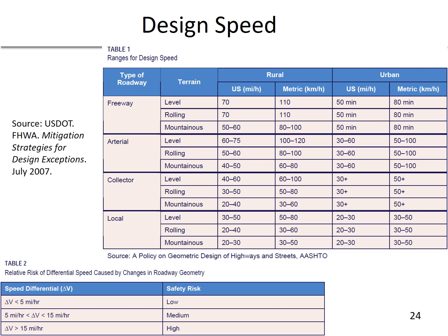Design speed is really not a specific design element. There's really not something you can go out to a roadway and necessarily understand the design speed. It really, though, impacts a lot of the other criteria. As we saw talking about these other elements, design speed plays an important and consistent role in a lot of those criteria, and it establishes a range of design values for many of those other elements.